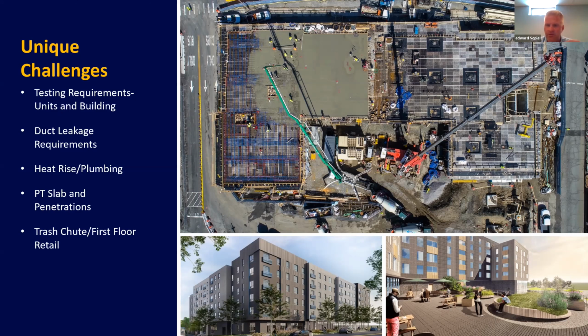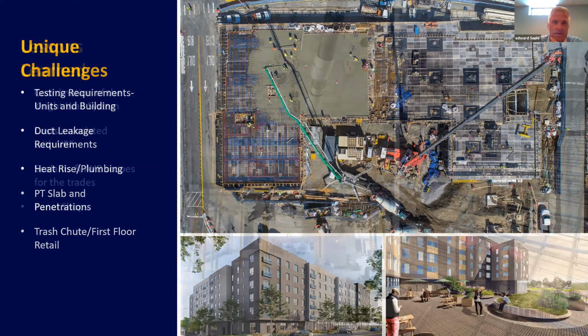And then also, somebody I think mentioned having drawings in different colors. Our contract drawings had, I think, 8 to 10 drawings that show the air vapor barrier throughout the building, all color coded by floor, by plan, by section. That is something your architect needs to do. It allows the subcontractor to understand the scope, which keeps the cost within reason. So there's no guessing. And then ultimately, you can't afford to have any mistakes in the field.